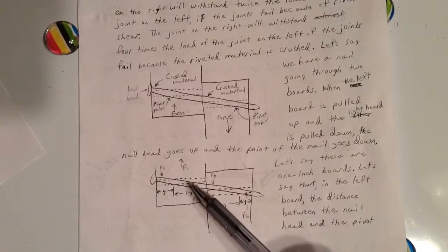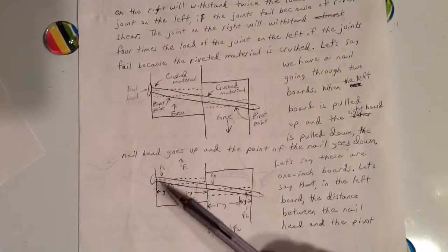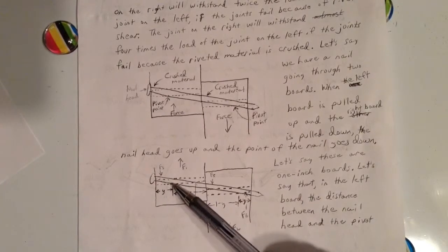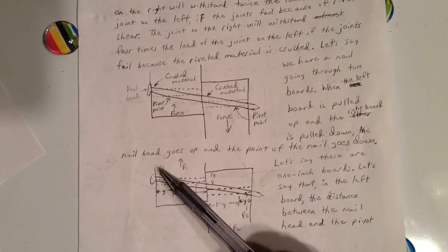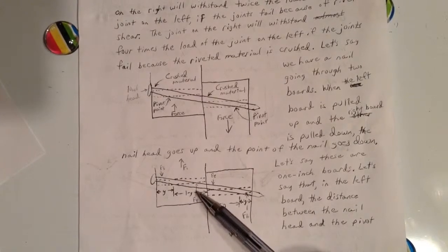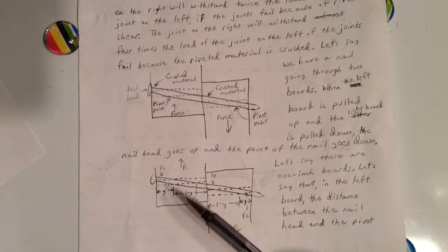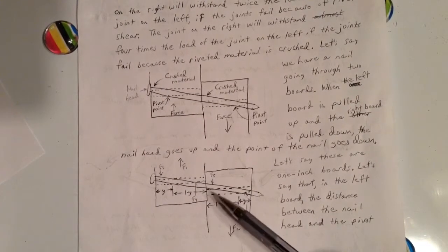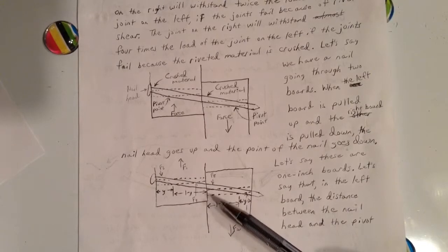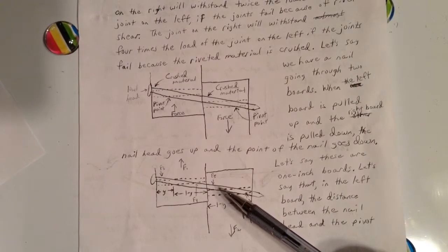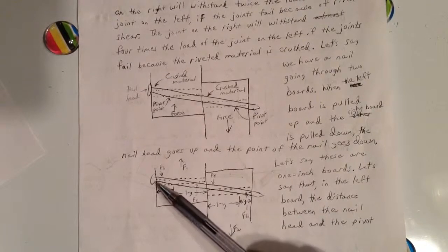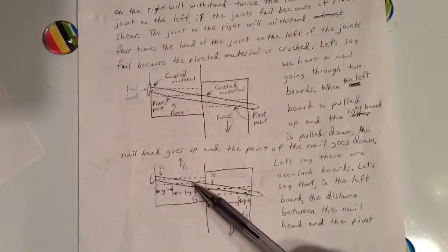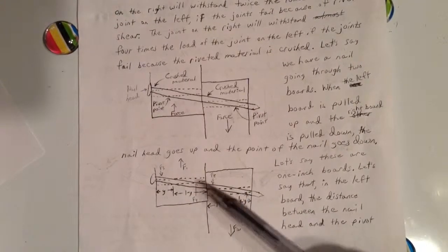That length times the diameter of the nail would be the area. Anyway, the ratio of their areas is y divided by 1 minus y. That's the ratio of F3's area to F4's area. So the bearing surface area of F3 over F4 is y over 1 minus y. The stress along these areas is likewise proportioned. The stress along the F3 surface area divided by the stress along the F4 surface area is also y divided